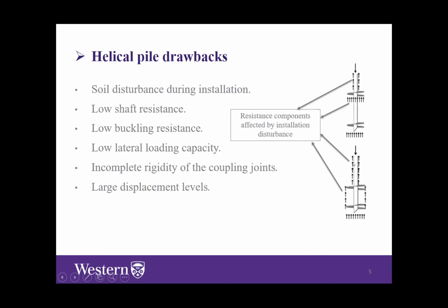Besides, if we are going to deep depths, we are going to add extensions to the pile, and these extensions need to be connected with some coupling joints here. These coupling joints are not completely rigid, so under high compression load, we might observe some lateral displacement due to the incomplete rigidity.